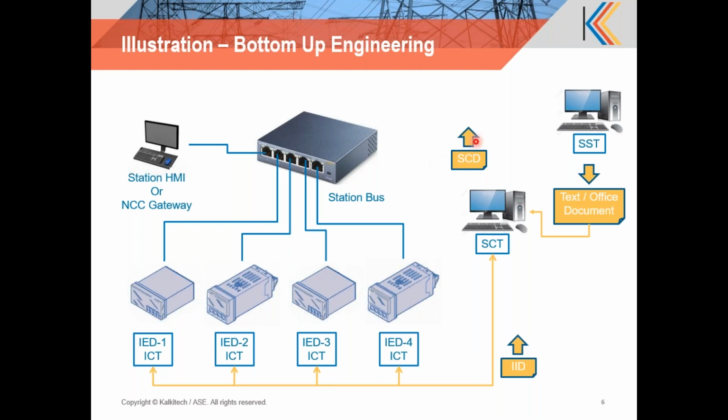But the SCD can still act as a global view of the configuration of the system, and this is something that can be archived and used later when there is a modification to the substation which requires re-engineering, and at that point of time it could use the top-down approach. There is no particular reason to avoid using that. The SCD can still be used to configure the client or the gateway.